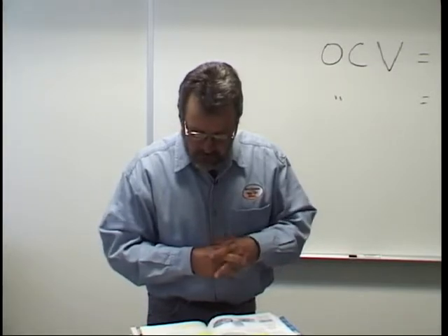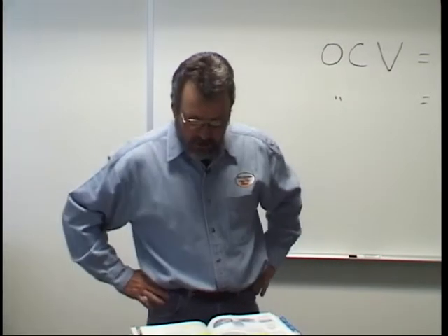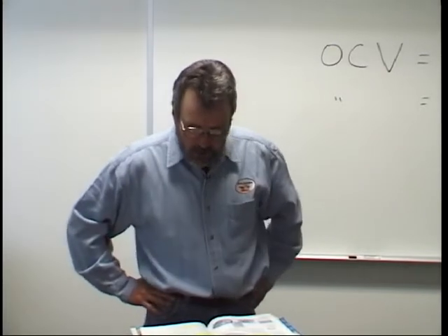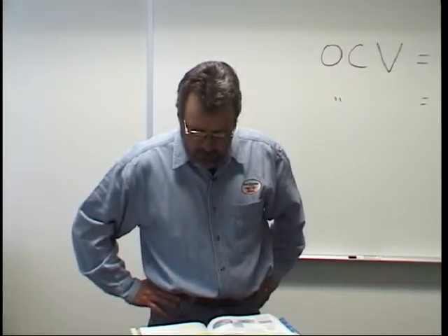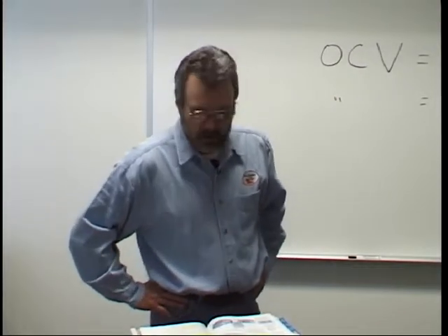If the gas shield fails to cover the arc or is contaminated, porosity results. Almost all porosity in the MIG-MAG welds is caused by poor gas coverage. Too much is just as bad as too little.